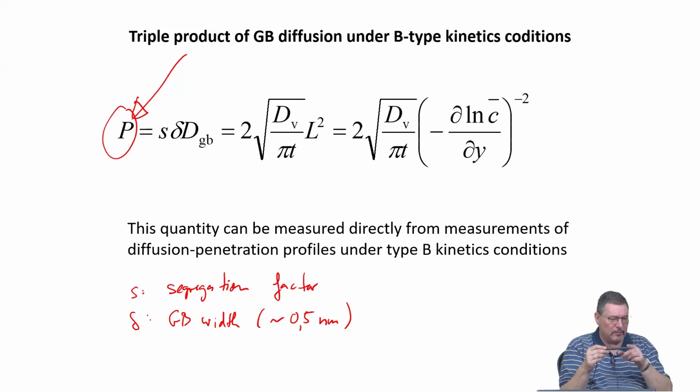And from knowing that they come from a certain given terrace and going through the multi-channel plate, you can reconstruct in 3D where the atoms you registered came from. So you get a 3D reconstruction atom by atom, but only of 50% of the atoms. And that gives you a very accurate description of grain boundary segregation, for example, right? Because you know, in this grain boundary, there were 3 out of 10 atoms of another element or so.